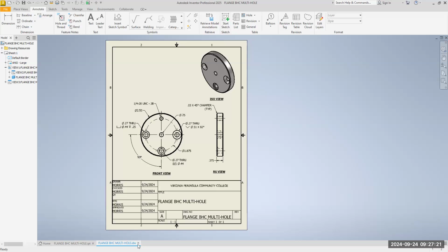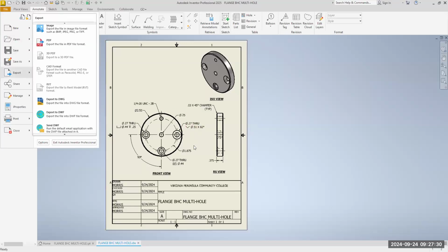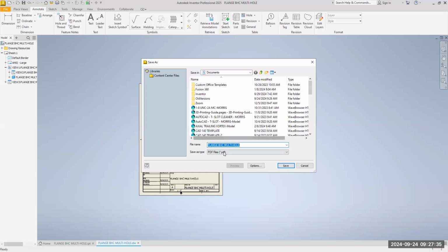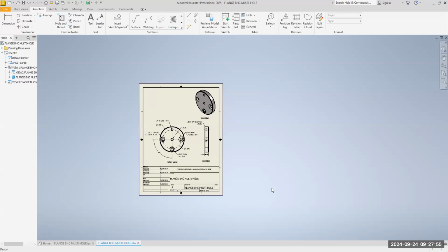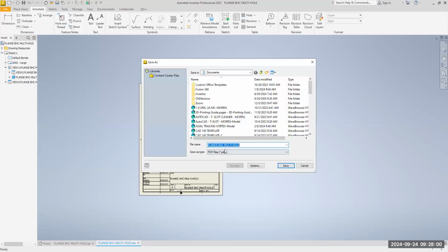All right, now go to file, export. I've got the drawing pulled up right now. Just select PDF. And it's going to create a PDF of that file. Then y'all can send your file to Dean Stabile. He can open it up. He doesn't have CAD on his computer, but he can look at your, oh, Stephen, you did wonderful, right? Select save. There's your PDF of your, one more time, file, export, PDF. There you go.